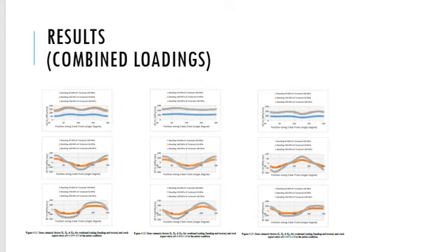For this study, three different cases of combined loading were introduced. They are, first, bending 50 megapascal and torsion 100 megapascal; second, 100 megapascal for bending and torsion 50 megapascal; and third, bending 100 megapascal and torsion 100 megapascal. Figure 4.11, 4.12, and 4.13 present the values of stress intensity with different loading combinations and different crack ratios.